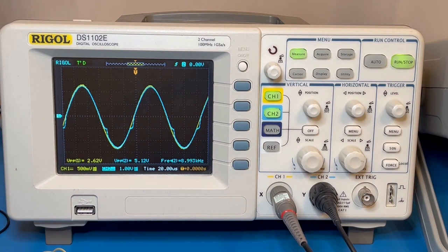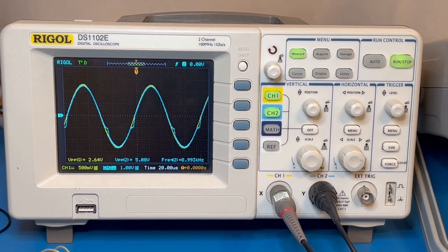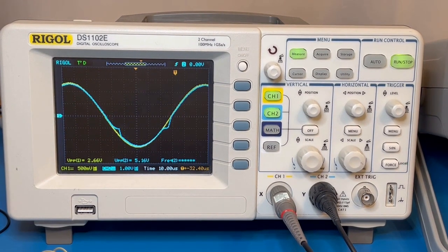We see what looks to be small shelves happening, sort of towards the middle of the waveform. So what's happening here? And this is on the output only. The input still looks clean. So here I'm moving the DC offset from the function generator, showing that it does not affect the voltage at which these shelves occur, since you can see it happens at the same points on the y-axis.